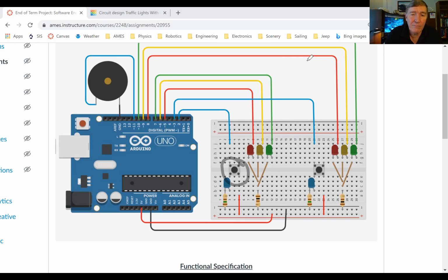This thing right here is a switch, and we've already talked about how it works. If I push the button, then it allows electricity to come up into the signal. And if I'm not pushing the button, then it does not allow electricity to come up. And now I've got this wired such that when we push this button, there's a blue LED that will automatically light up. It doesn't light up because the Arduino told it to.